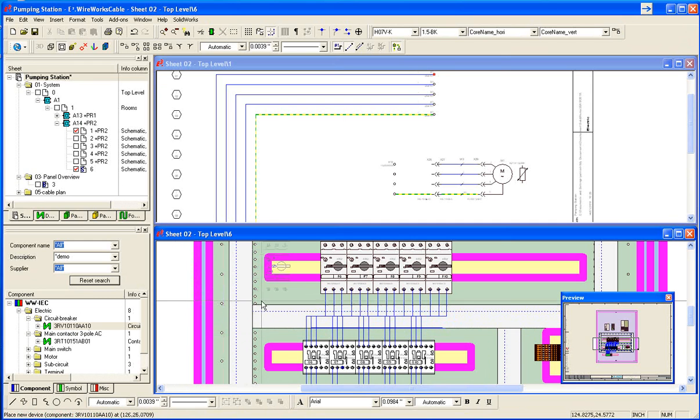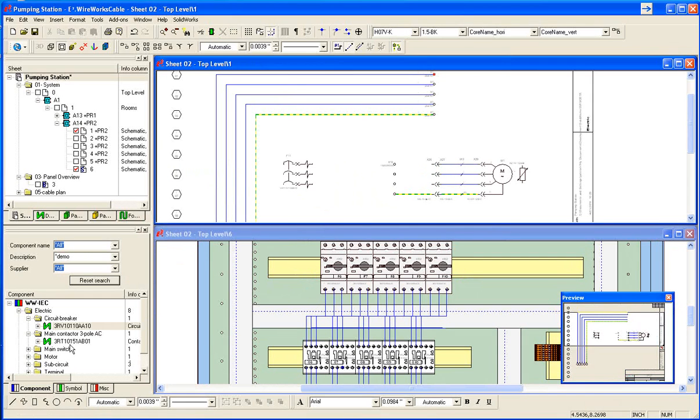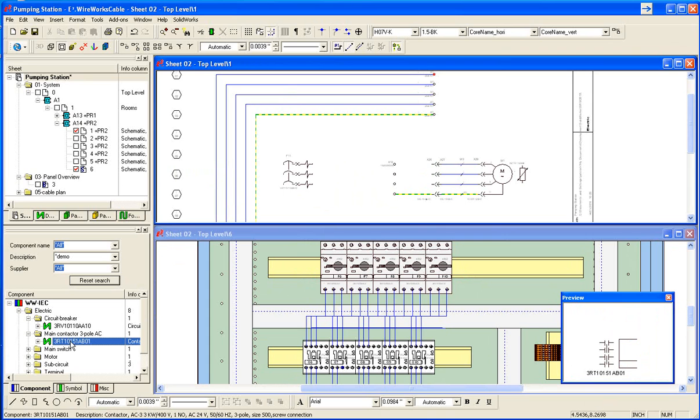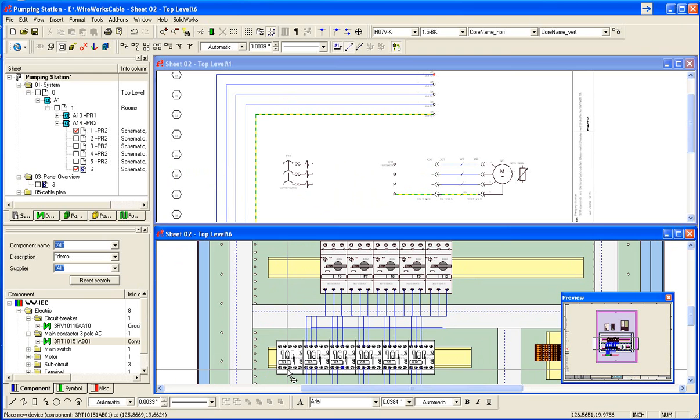It's also presented with valid mounting positions, so it snaps very easily: drag, drop and click, snap into the panel sheet. If I go up to here, you'll see it goes into the schematic sheet, and I can place that down in the schematic. Alternately, if we go in here, I can pull out my panel element like so and drop it onto the DIN rail like this.